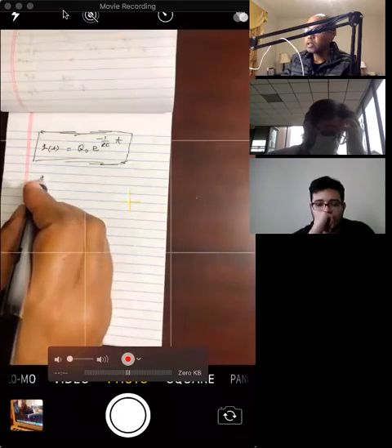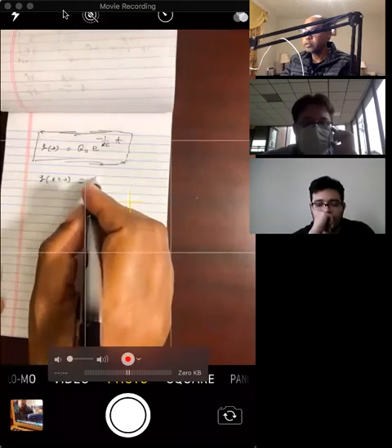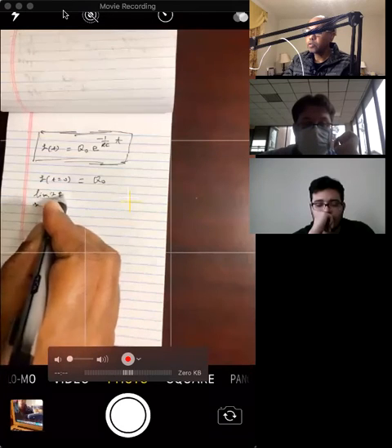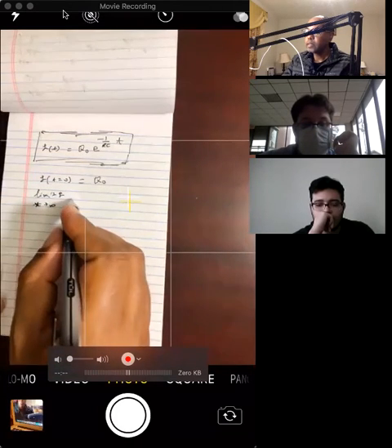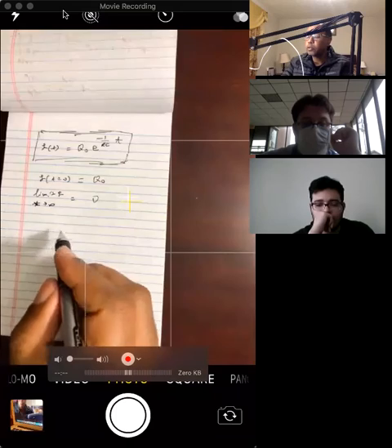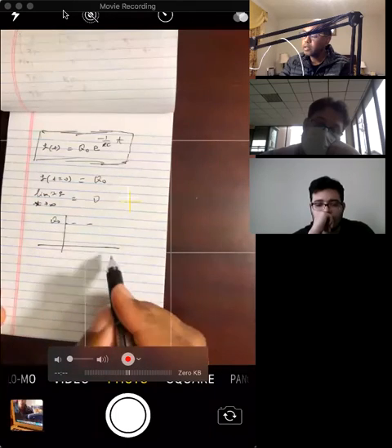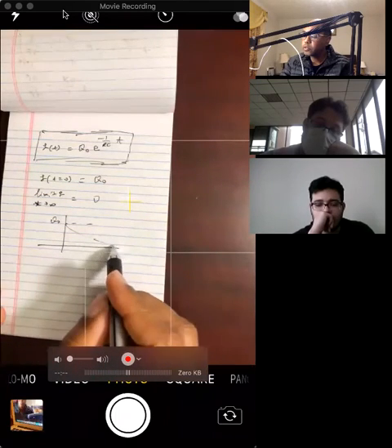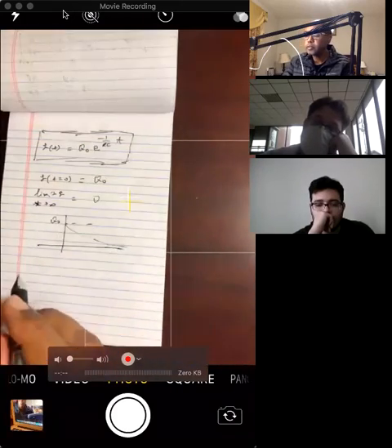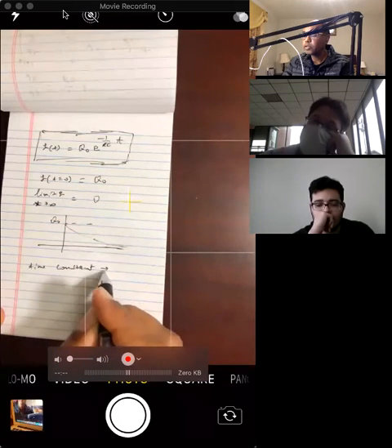So let's plot it. What is Q at t equals 0? We have already stated it. This would be Q naught, so we start with Q naught. How about the limit of Q as t approaches infinity? That's going to be 0, right? When t goes to infinity, this goes to 0. So we can plot it now. The initial charge is Q naught over here, and then at infinity, it goes to 0 like this. How fast it goes depends on 1 over RC. So the time constant in this case is also 1 over RC.